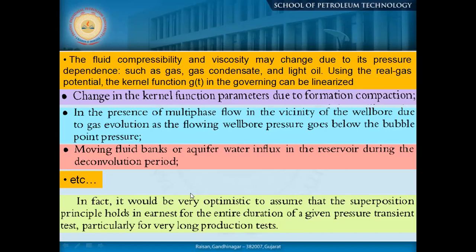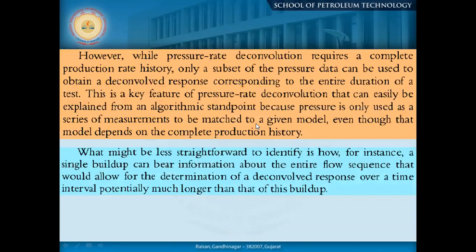Okay, so it would be very optimistic to assume that the superposition principle holds in earnest for the entire duration of a given pressure transient test, particularly for very specific information of your wellbore. Okay, so that is the production test, a very long production test. That is how we are trying to eradicate certain inconsistency and get the data. Okay, so that is one part which is very advantageous. If our deconvolution parameters for different tests are really matching, that means we have really linearized.